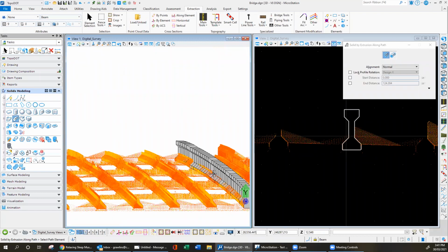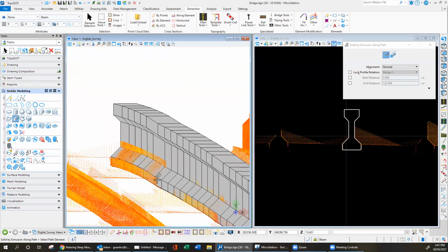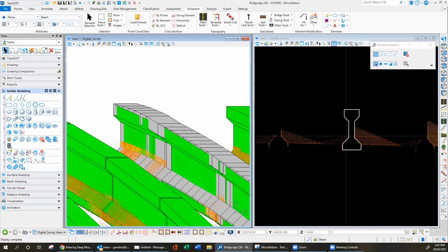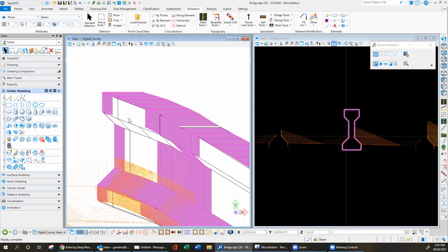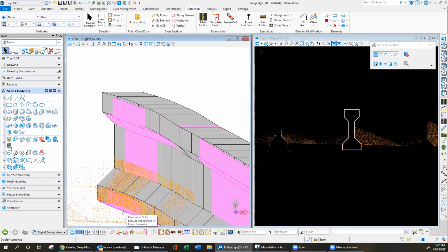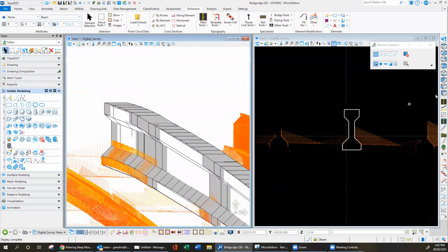So the sections over the piers are quite low. You can see there is a doming effect as it goes over that last segment. All right, and if we do a little quick comparison with our original straight extrusions, you'll see that the straight extrusions just simply don't pick up these rises and these deviations in the concrete beam. So it's far superior to those original ones. And if we have a look at the 2A ones that we placed, the drape line hasn't really followed it exactly. We would need to have done a lot of QA on those to make sure that they did follow those heights exactly.